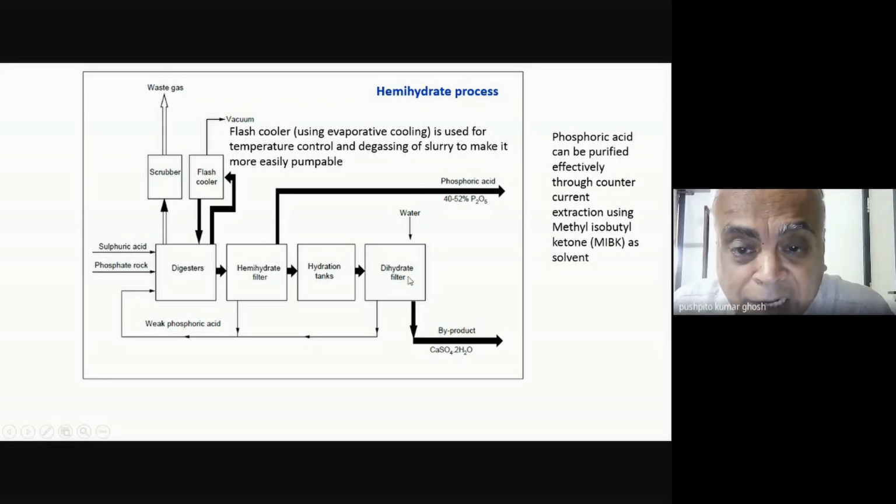So you are ultimately making the dihydrate, but you're doing it after the reaction, not during the reaction. During the reaction, you made the hemihydrate. And the ingenuity of material science, of solid state physics, etc., all comes in here: how to do that smart stuff of inhibiting the CaSO4 half H2O from solidifying on you, and at the same time, in a controlled way, hydrating it so that you ultimately end up with the dihydrate.